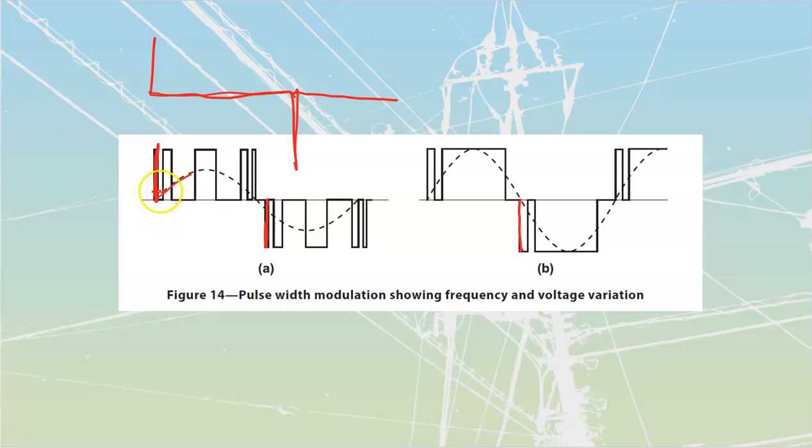What I do then is I just apply more spikes. More spikes means that I've got more high values of voltage compared to values of 0, and therefore a higher average value of voltage. All that the PWM-driven load is looking at is, over the last couple seconds, what's my average? Then I'll put that in as my average. If I use the same measurement over here, now I see a higher average. And over here, a higher average again. And that's how we get this synthetic AC that's going to come out.